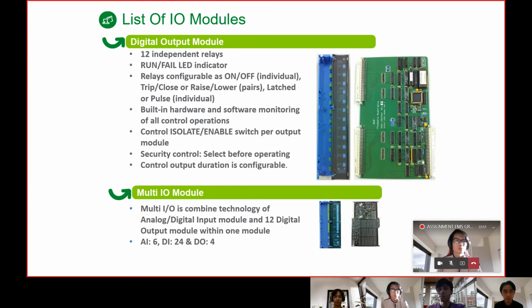We have 12 independent relays, run or fail LED indicator, relay configuration as on and off individual, trip or close or raise lower pairs, latch or pulse individual, built-in hardware and software monitoring of all control operations, control isolate or enable switch per output module, security control, select before operating, and control output duration is configurable.